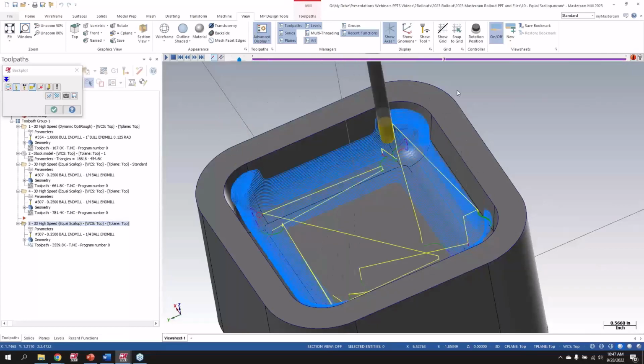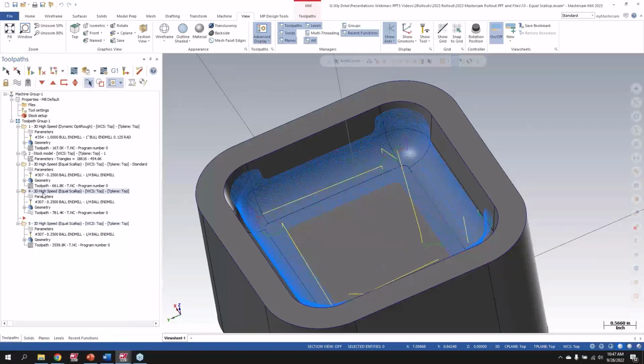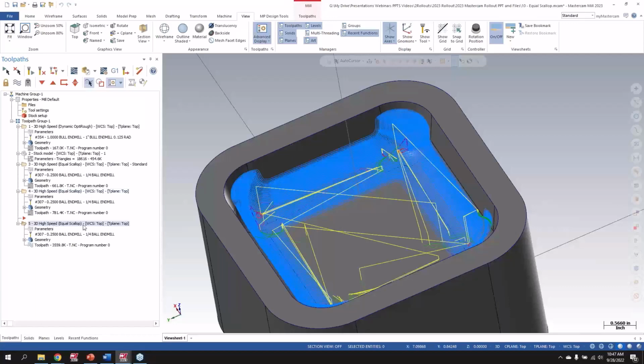And it might not be a full 5. I think this one is actually only 3, but based on my step over, I'm just giving it more room to move. In my first example in operation 4 here, I was forcing an absolute single pass with that option turned on. But here I can give it more room to create additional passes based on my step over. So even though there's a bit of a workaround on how to get it to work with a ball nose, I still think there are a lot of use cases here, especially for anyone doing intricate 3D machining, that I can apply this to parts.